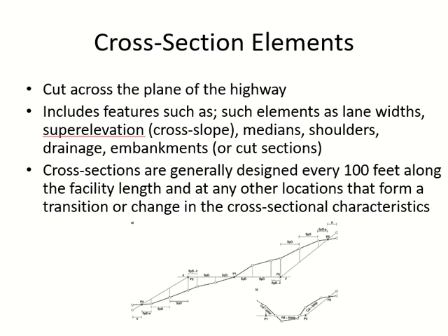But if there is a change, say after 50 meters there will be a curve, it will change the cross section of the road. So now you will not wait for the 100 meters because you will miss the change. The point of change should be covered in any case, whatever the distance is, 100, 10, 1, whatever.